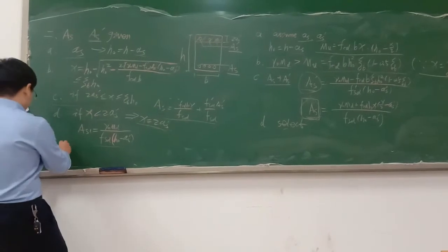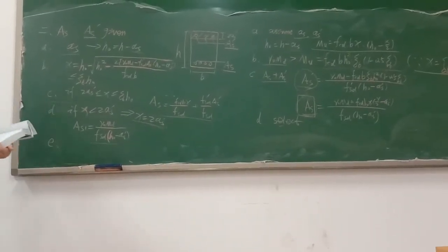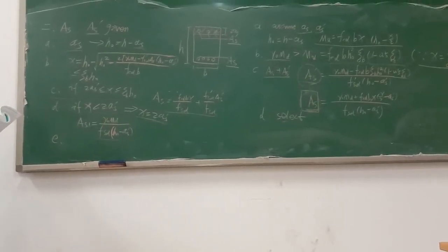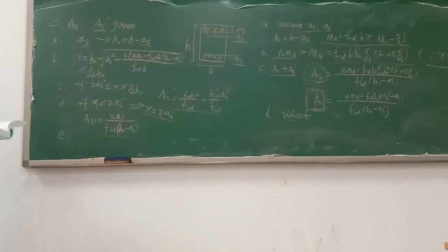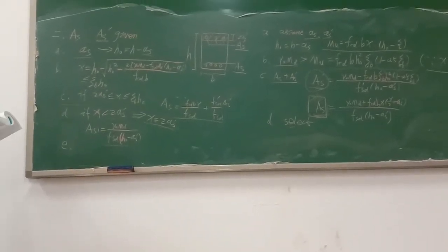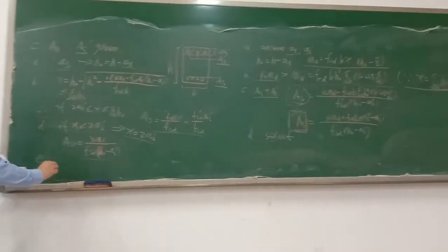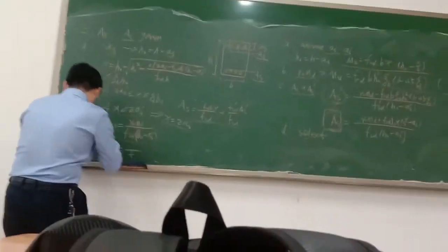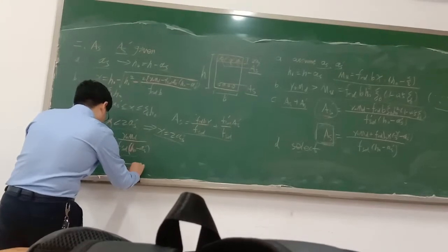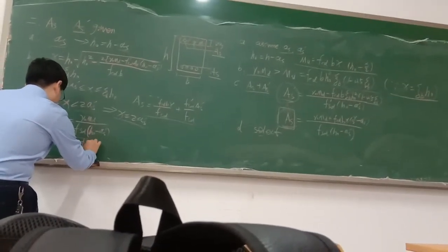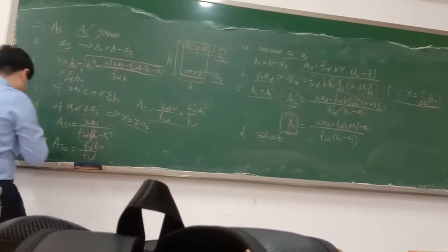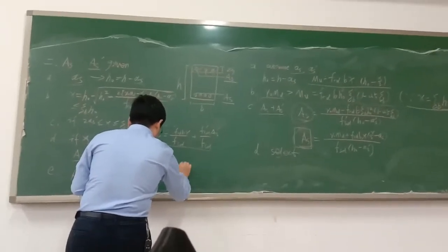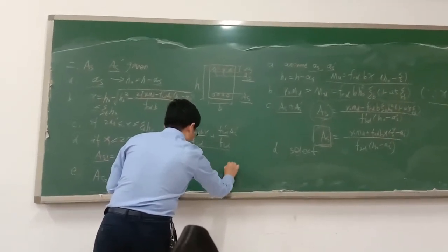And another step, we calculate for the single reinforcement section, A_s' is not considered in the equation. So that means taking A_s' equal to 0. Then we get another A_s equal to f_cd b x divided by f_sd. Then we compare these, we use the smaller value of A_s1, A_s2.